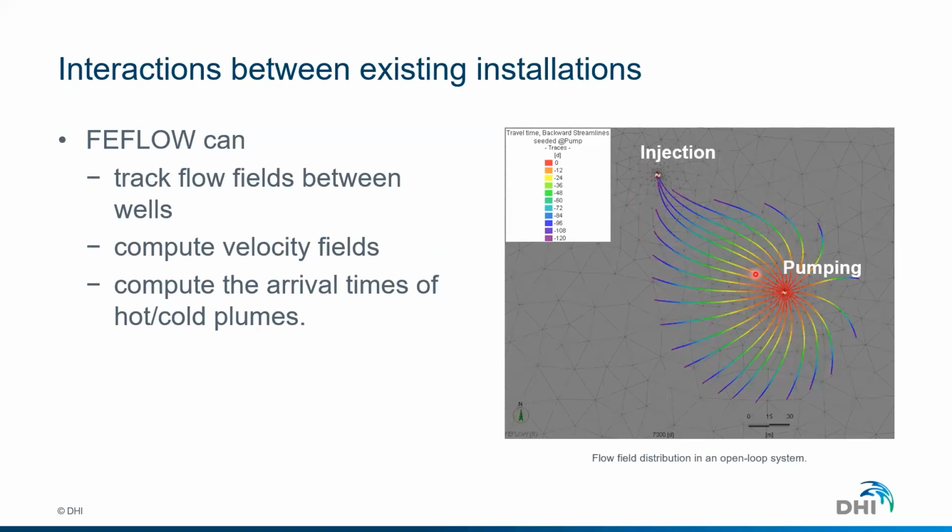In this case, which is very exaggerated, it takes about 120 days to travel from this point to this point here downward. So you can estimate these times and then see whether it is worth having the boreholes at these locations, or maybe you will need to modify them to fulfill your modeling objectives or your project objectives.